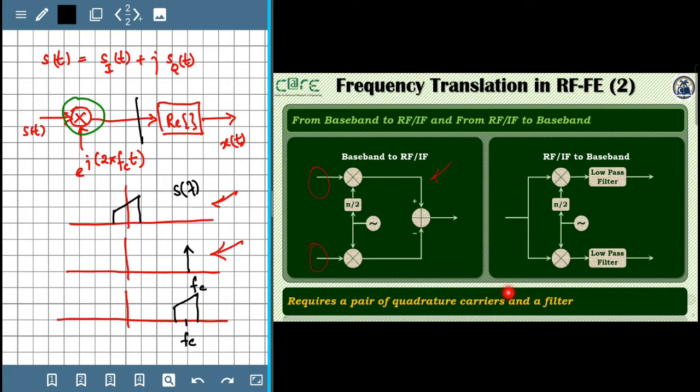In the frequency domain, that would basically correspond to taking the complex conjugate and flipping this spectrum along the frequency axis, and then adding the two to obtain the resulting spectrum at the output. So if we want to draw the spectrum of x of t, the flipped version of the spectrum will also be superimposed.